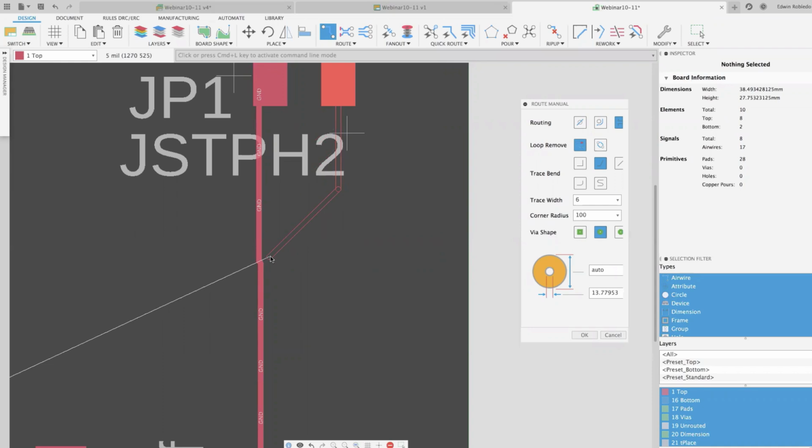On really, really dense boards, this could be very useful because let's say, for example, you need to make a modification to a schematic. Therefore, maybe the connections actually get modified on the circuit board. You may have already had, say, 75% routed. Instead of having to get rid of those traces, you actually could invoke the push and shove. That way, it plows its way and it'll move everything out of the way.